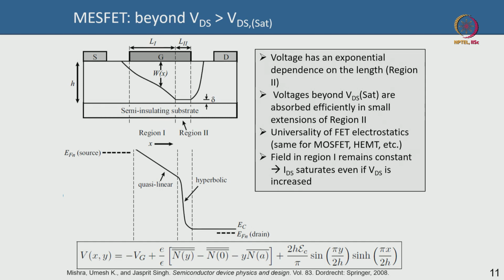If you look at this image, when I say pinch off, the channel pinch off, not the gate pinch off, I am talking about the channel pinch off above a certain drain voltage. Above a certain drain voltage the current saturates. We call that the depletion layer thickness having pinched the channel off, but in reality it is not a 0 thickness. In reality there is a small amount of opening remaining, which is called delta, provided the gate is not completely pinched off.